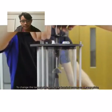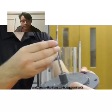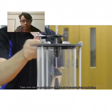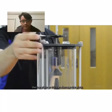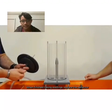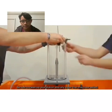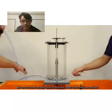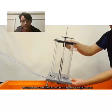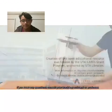To change the target plate, undo the knurled screws on the top plate and remove this from the transparent tank. Take care not to over-tighten the knurled screws when replacing the top plate as this can damage the plate. When finished taking readings, replace the deflector back to the first one used. Be sure to clean up your station and any water that may have spilled following the lab manual. Complete the results table and put together your lab report. Thank you.